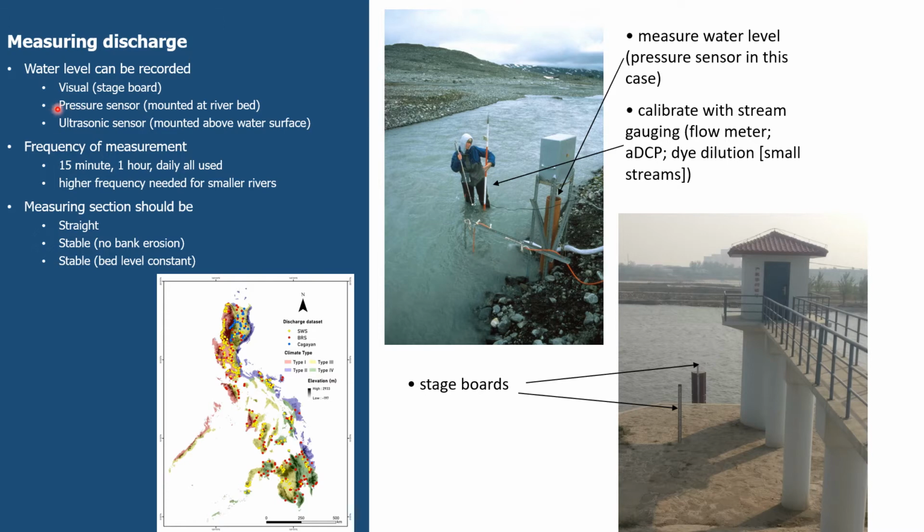It became very common 20 or 30 years ago to use pressure sensors. We've got one of those in this tube here, a pressure sensor at the bed, and the pressure sensor measures the depth of water above it. Very easy piece of equipment to use, very reliable, and gives an accurate water depth value.